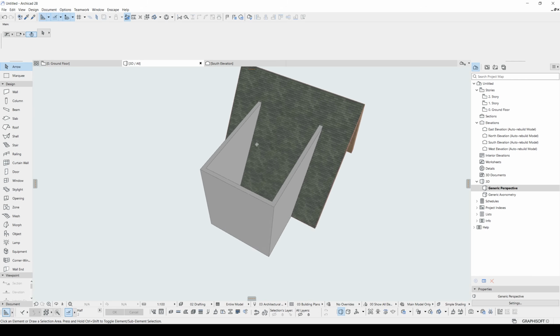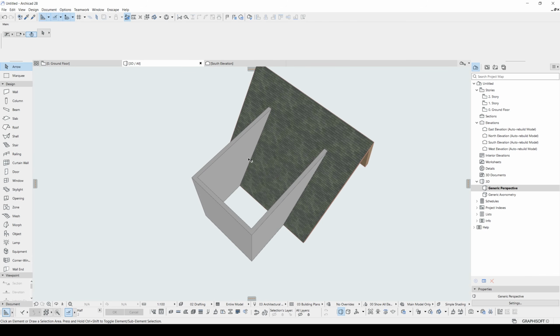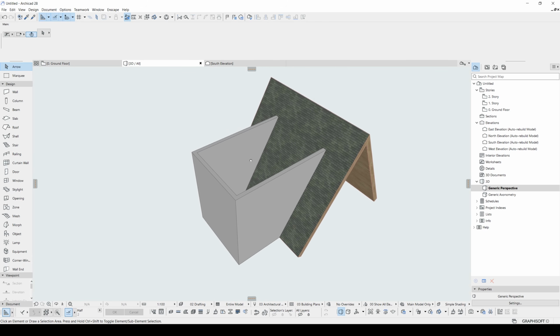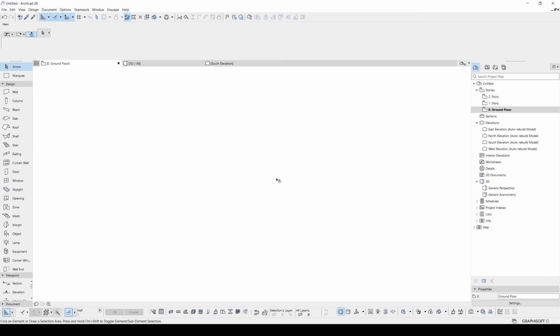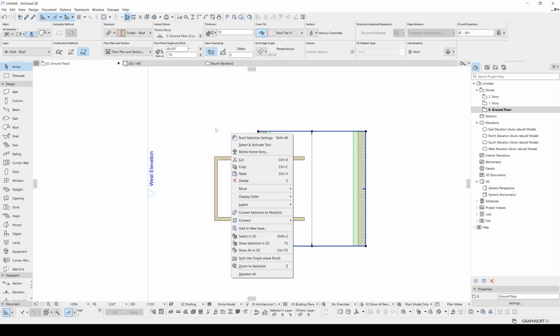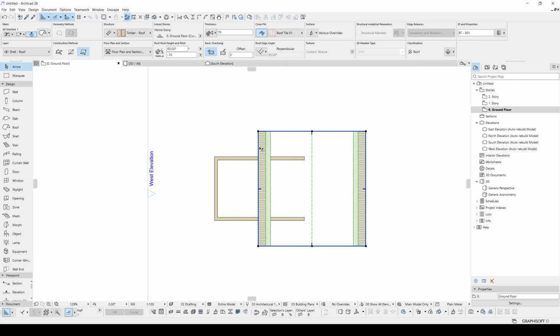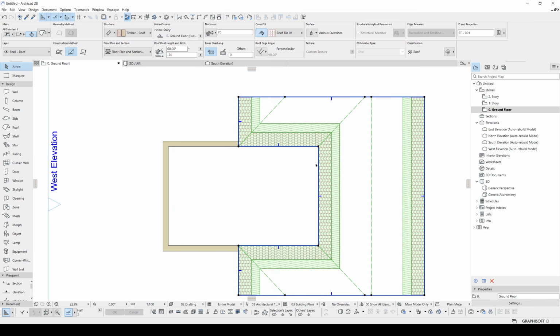We need to make an opening in the roof because this will be a unique and uniform room. So we will right click the roof, but okay, instead of that, let's just click the edge of the roof and click subtract from polygon. We will use this rectangular option and make an opening like this. But we have a problem. We have changed the blue part of the roof.